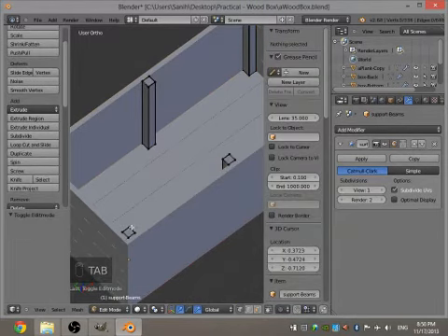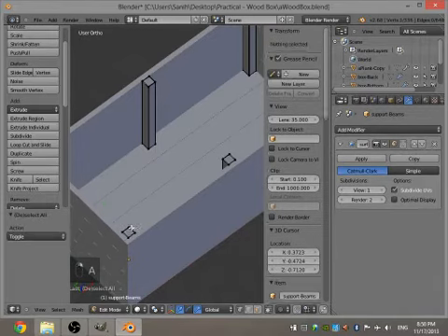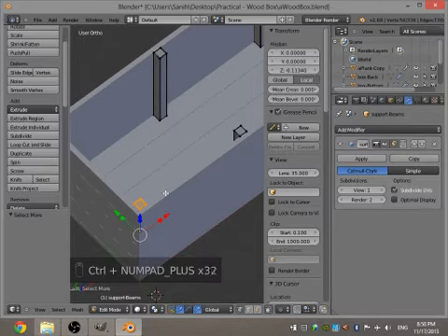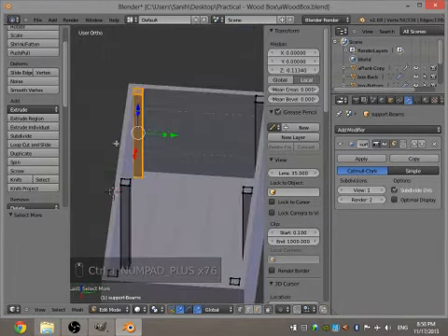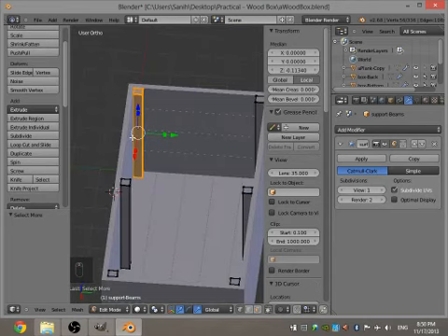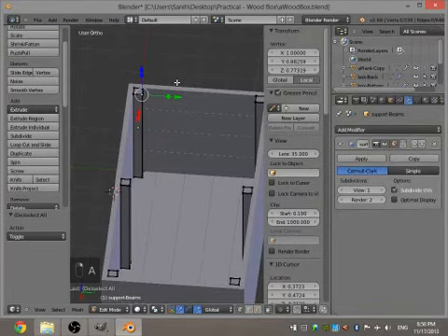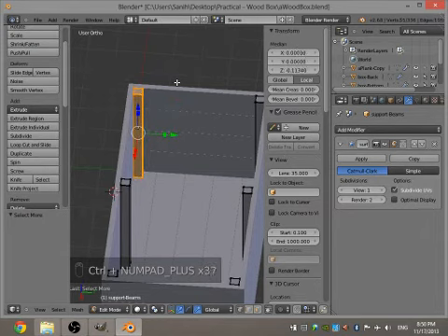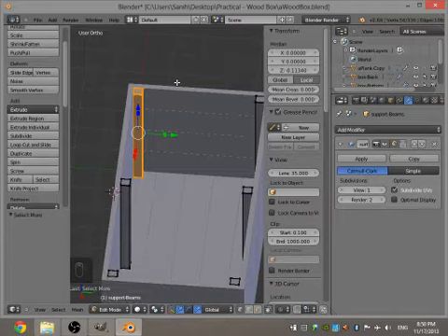I want only one piece, yeah. So I'm going to pick one of them. Right? I'm going to right click one of them, Control plus. And remember, I told you, when you Control plus it, you're going to be grabbing everything to do with that mesh. Okay, watch. I'm right clicking it and then Control plus, and it's increasing the grab. And then I hold it for a while, and when I know that I have grabbed everything, then I'm done. If it's a very complex mesh, you might have to hold for a while to grab everything.